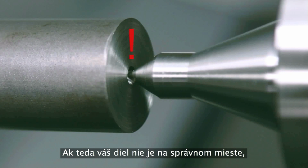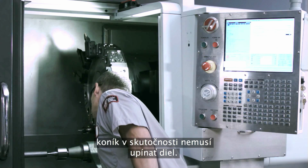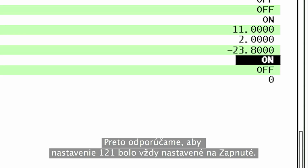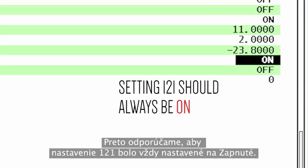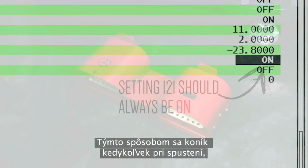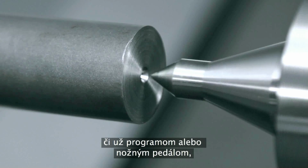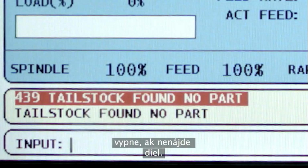So if your part isn't in the right place, the tailstock may not actually be clamping the part. That's why we recommend setting 121 should always be set to on. That way, anytime the tailstock is activated, whether by a program or with the foot pedal, it will fault out if it doesn't find a part.